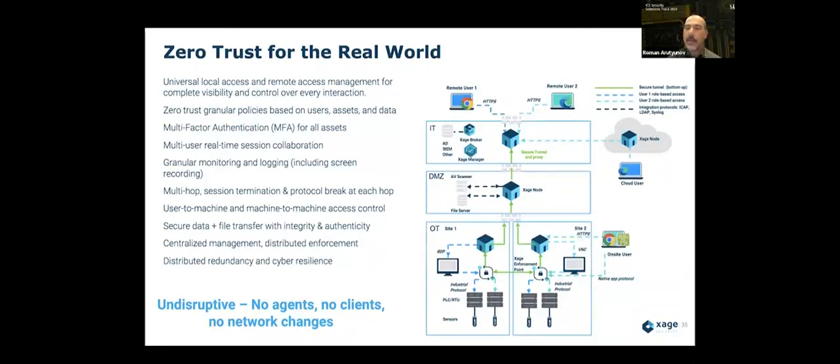It will then proxy and relay. Once you select the asset you want to go to, it'll proxy and relay across multiple layers and instantiate a temporary session for you on this workstation in here. Dynamically orchestrate a ZTNA enforcement point to allow access to a single PLC that you've selected.